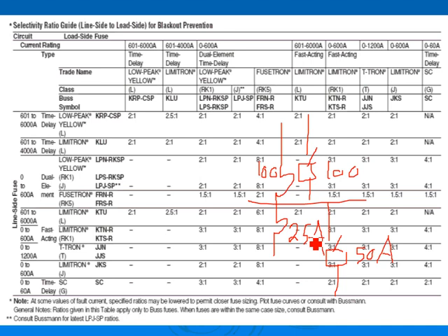Well, all you're concerned about is that I'm taking a feeder here, and I'm going to tap it. Now this has to be half of this. So let's just say it's a fuse. If that was a fuse right here, disconnect, so this will be half of this. 50 will be what? 25 here. Do you see what I mean? And you keep going all the way down. Does that make sense? So you start from the largest, then you take that one, half of that, all the way through.